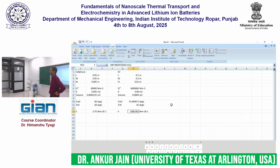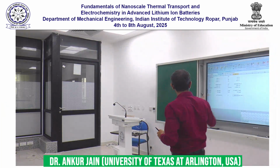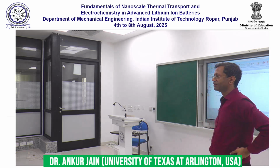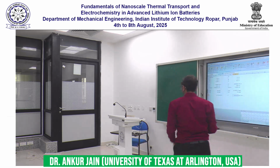So what this means is that if the convective heat transfer coefficient that you can provide is only 1000 watt per meter square Kelvin, then your cell will be at 75 degrees C, not at 60 degrees C. Are you willing to live with that? That's the question that your company will then have to answer. You can also go back to them and recommend making your cells smaller, either less in thickness or less in size, right? Those are all the kinds of design questions that you can possibly answer from an analysis like this. Okay, any questions?